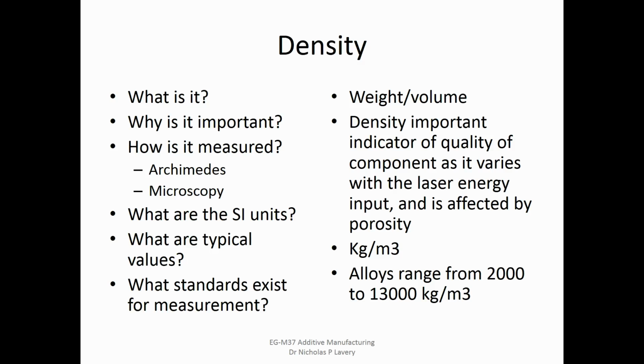So at that point you tend to rely a little bit upon microscopy. You'll section the part in various ways, take lots of small images, as small as you can, patch them together, and threshold them in such a way that you can pick out porosity. For very low porosity parts, you'll typically have maybe a little bit of what we call macro porosity, maybe a couple of 20, 30 micron size pores that are clearly there, but what you can't see from that is your micro porosity. Anything below 1 or 2 microns becomes very difficult to see and capture.